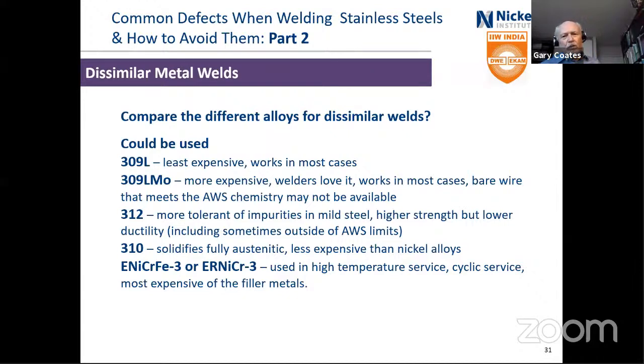309LMo works similarly very well. It's a little bit more expensive. It flows nicely as a weld metal. The welders love it. In many cases they say, I want to use that filler metal, and yeah, it works similarly in most cases.